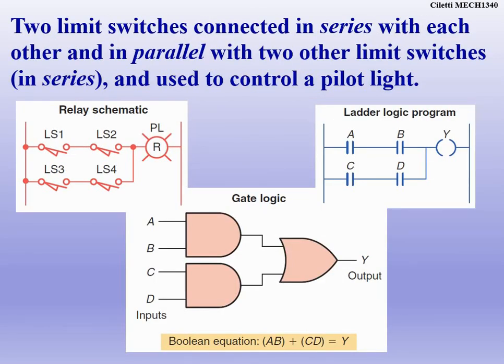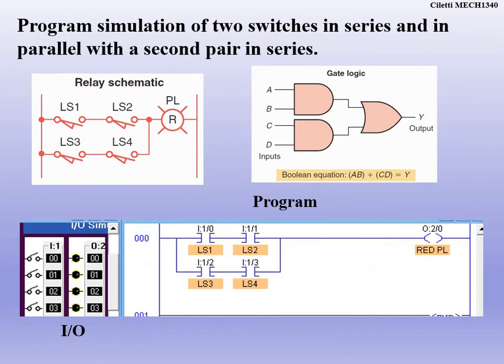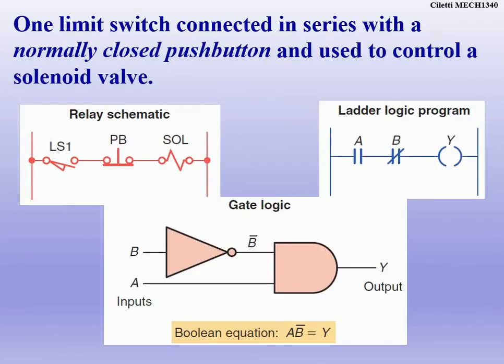Same thing here. Just pause these and take a look at it. We have A and B or C and D that will create our output. So I think we can really see how everything is coming together, and we can go from our schematic to our logic gates, and then take our logic gates and create our ladder program. Same thing here, just seeing the same things in the Allen Bradley program.